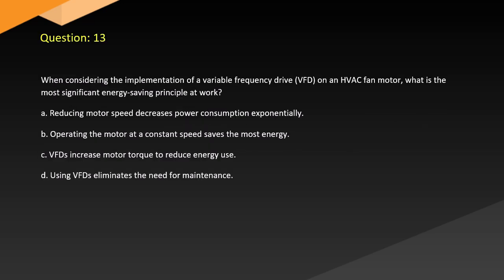Question 13. When considering the implementation of a variable frequency drive (VFD) on an HVAC fan motor, what is the most significant energy-saving principle at work? A. Reducing motor speed decreases power consumption exponentially. B. Operating the motor at a constant speed saves the most energy. C. VFDs increase motor torque to reduce energy use. D. Using VFDs eliminates the need for maintenance.